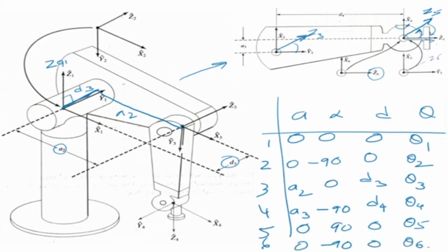Now something very important to note here is that for many manipulators, if you just multiply out the transformation matrix T0 to 6, equated to the desired position orientation matrix, you may not be able to solve. Now in this particular case also, we are not able to solve.